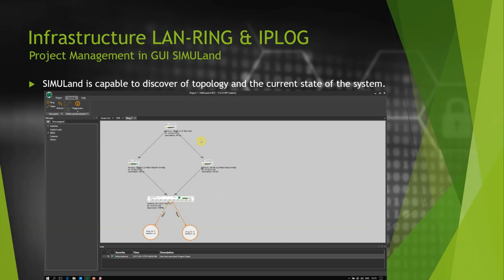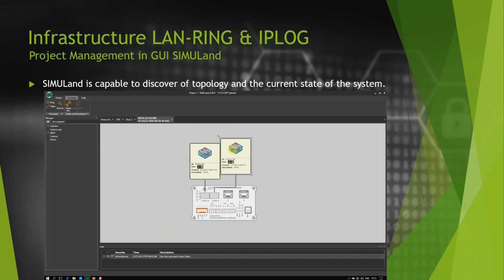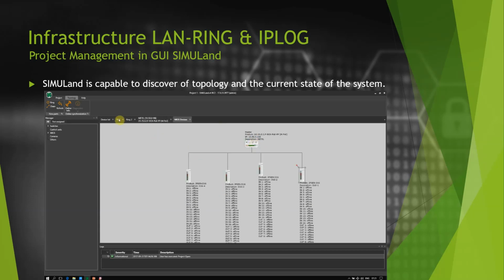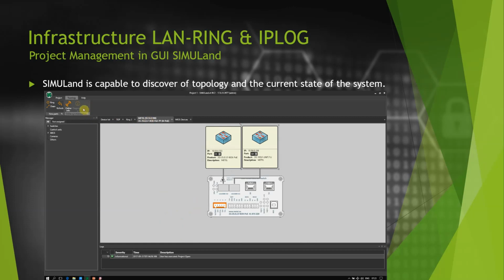This workspace is called the ring or non-ring. The detail workplace displays the device's front panel and the devices connected to it. From this workspace, it is possible to go to the MEOS connected to the device. The TOP, ring, and non-ring workspaces support diagnostic tools such as data traffic, line status, ring status, RSTP, and more. Detail and MEOS are used to read the operating states. The online info tool allows you to view port activity, input-output states, power values, PoE status, LED status, and other information.